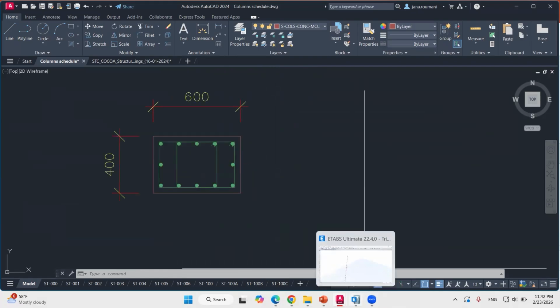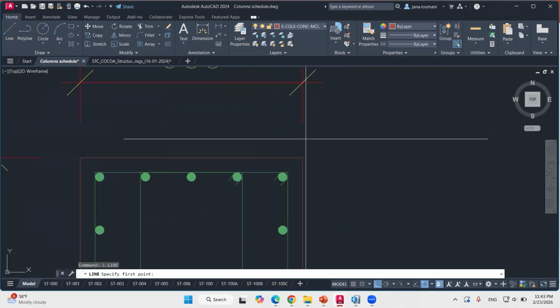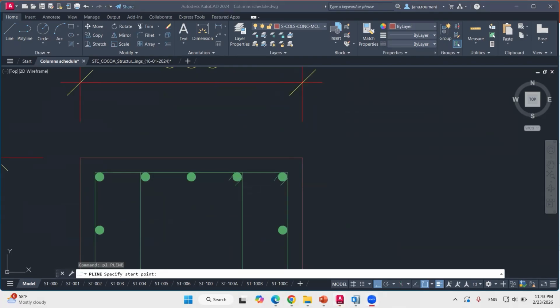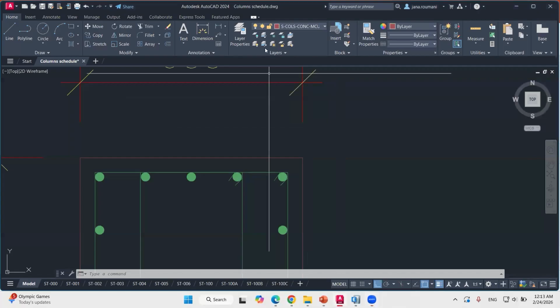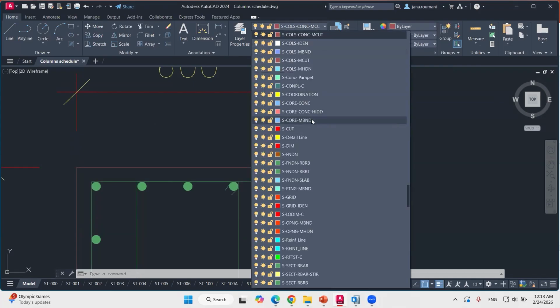We also need to mention how to calculate the diameter of the bar. Of course, in order to do the column schedule, we need to inform the construction workers on site and construction engineers of the diameter of bars we have and the diameter and spacing of the stirrups in order to construct the column accordingly.